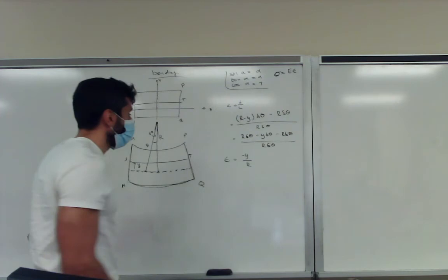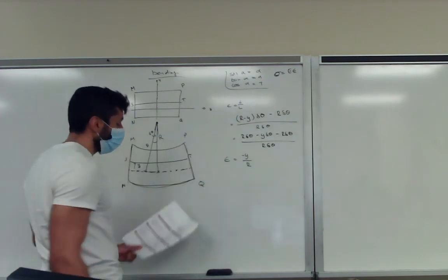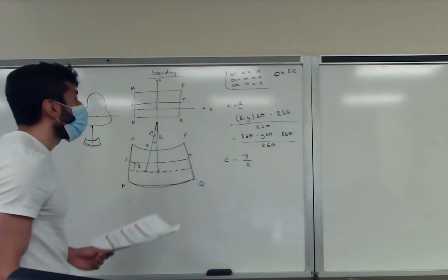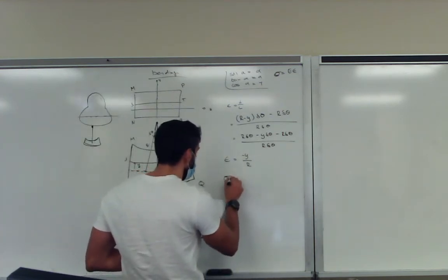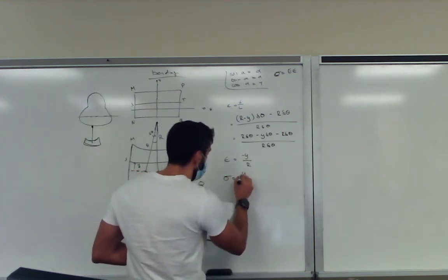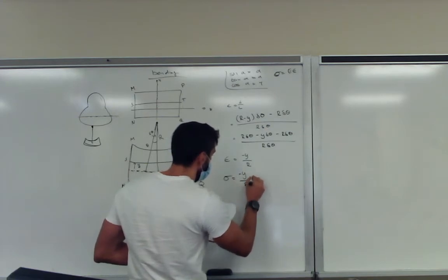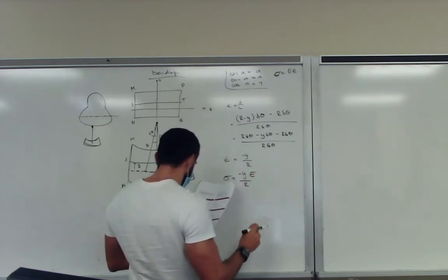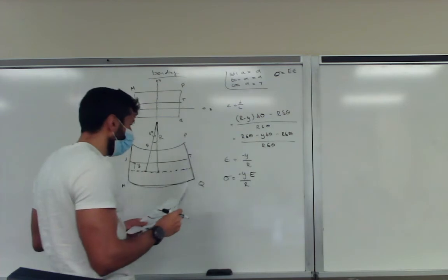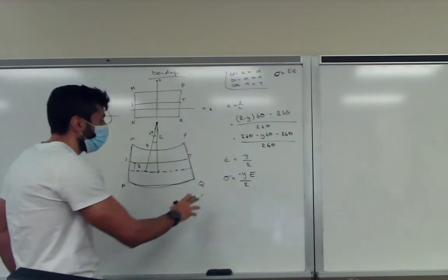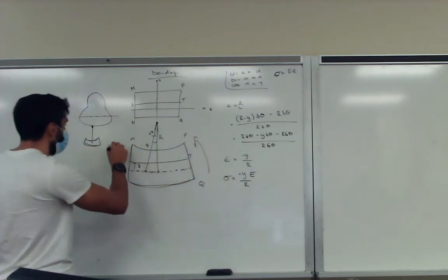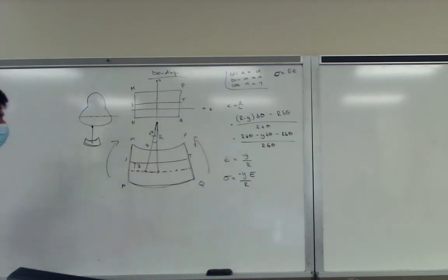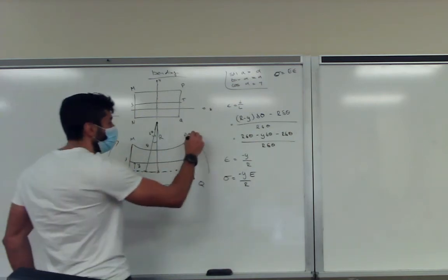So now if we want to go to stresses, we basically multiply by the Young's modulus. So our stresses are minus y over r multiplied by E. And if you want to go from stress, note the key point was eventually going into the definition of bending moment.